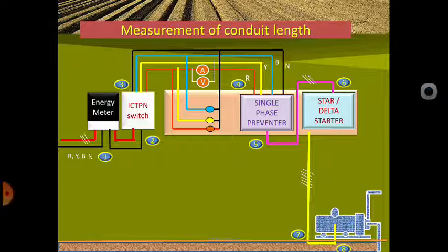From 6 to 7 it is coming to the nearby wall. At the same time, 30 centimeters will enter into the depth of the ground, as we are using underground wiring. So it avoids any problem, and it goes to a depth of 30 centimeters. It is running on the floor for nearly 2 or 3 meters, and from there it goes 30 centimeters up to the plinth. From that 30 centimeters we are going to give the terminal box.